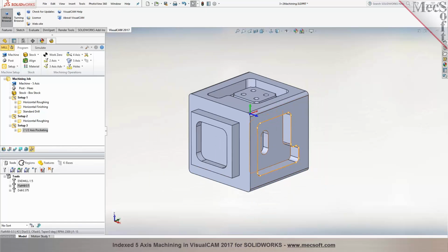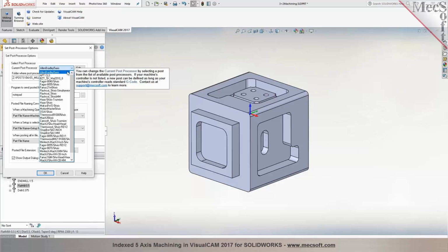Yes. Once you have all of these programmed, you have your post. We would need to provide you a 5-axis post. We would need to develop one based on the machine configuration, so we can take one of the existing 3-axis posts and update it to a 5-axis. So once you have it set up in here, right-click and do a Post All. It will post and compute the angles for each of these orientations. Wow. Okay. So that will make everything easy. Yes, so I'm going to go ahead and show you a sample output in here, so just give me one moment. I understand pretty much all your explanation until this point.